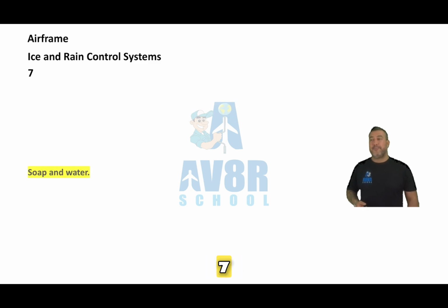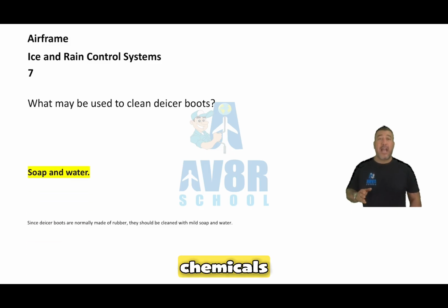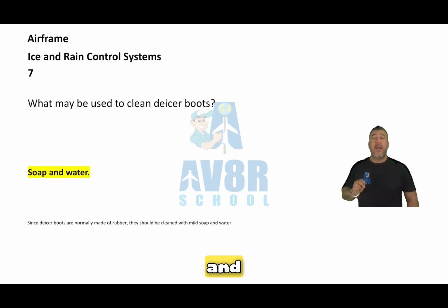Number 7, soap and water. What may be used to clean de-icer boots? No chemicals, only soap and water. Soap and water is what you use to clean de-icer boots.